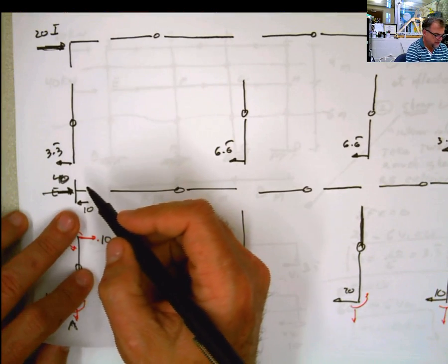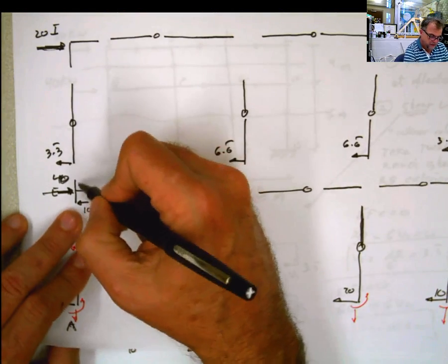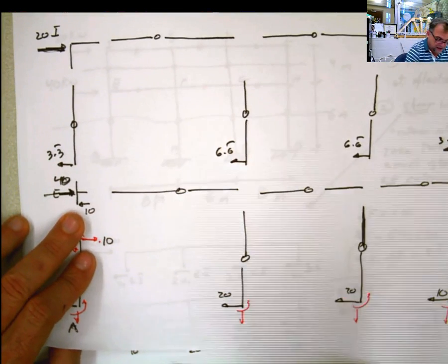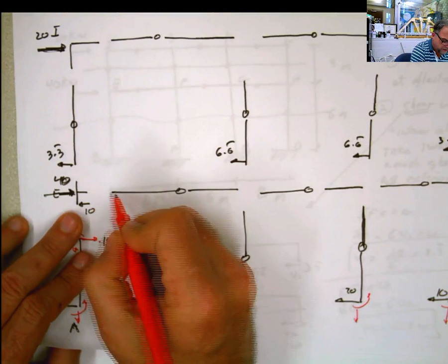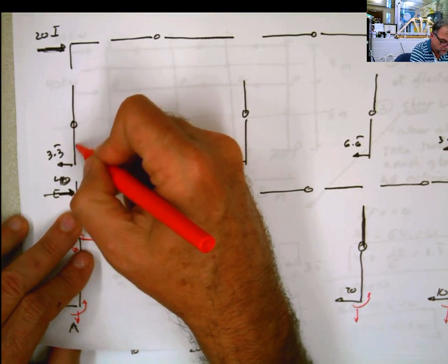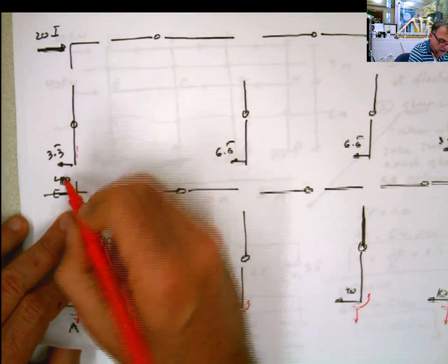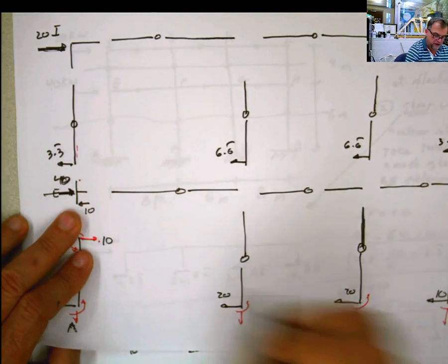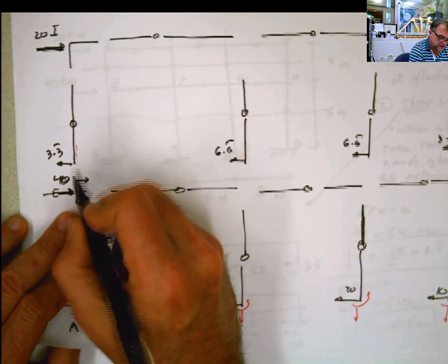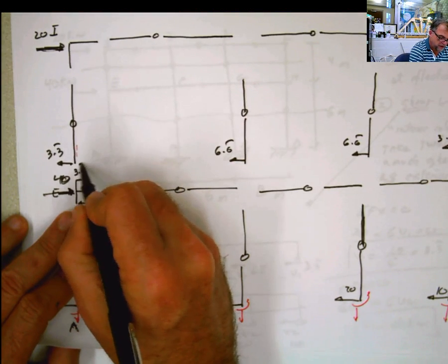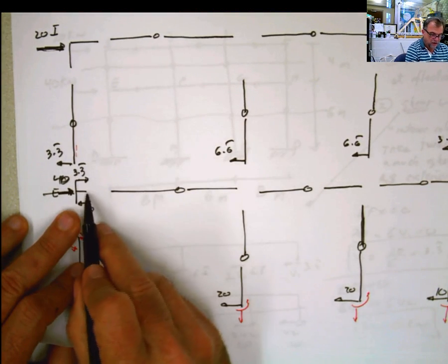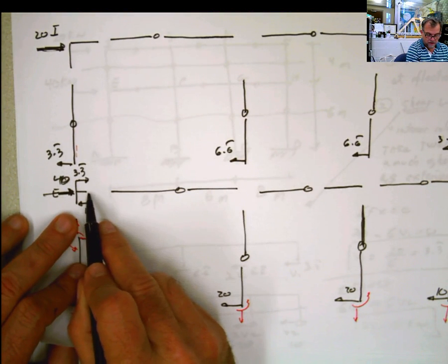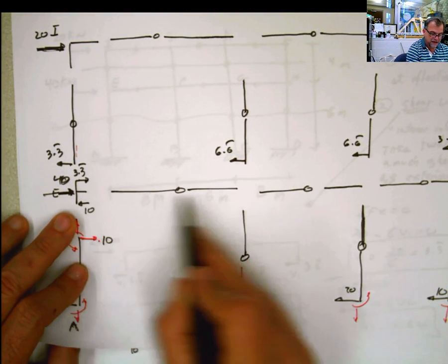what happened is that I need something here and I need something here in that joint. I have an axial force coming here from this beam, and I have another axial force coming to this joint from this column. Now this 3.3 is going to be transferred to this end, 3.33 in the opposite direction as I had it before, 3.3, like that. The only unknown is the force here, horizontal force, that is going to be the axial in this beam.